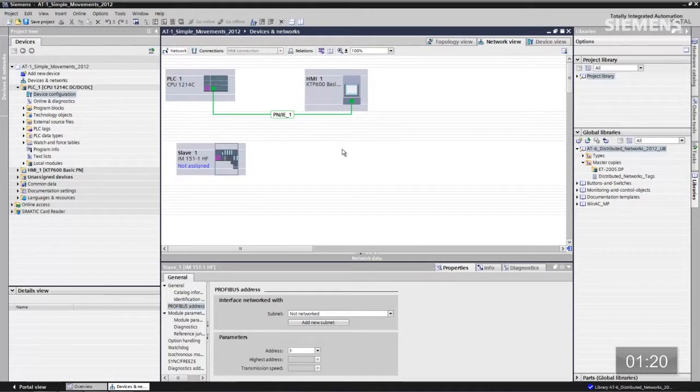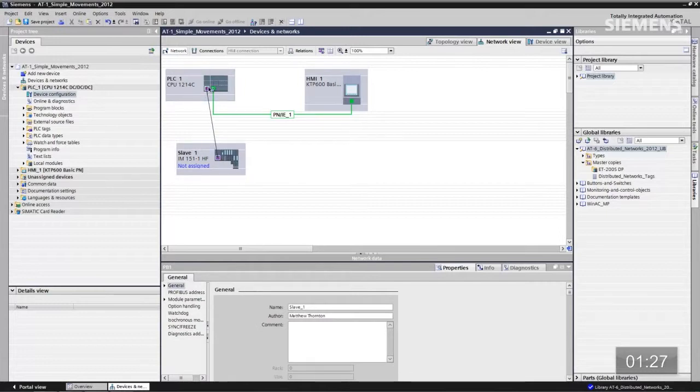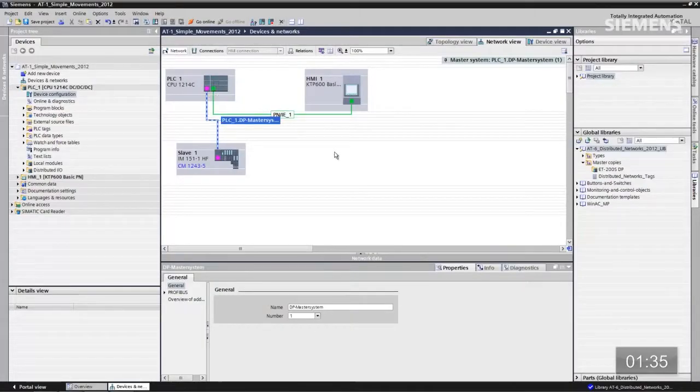The next logical step is networking. Let's just mouse over the Profibus interface of this rack. Let's drag it to the master module. When I let go of it, it'll auto-create the logical and physical connections. The Profibus network is done. Let's move on. Okay, Profinet.